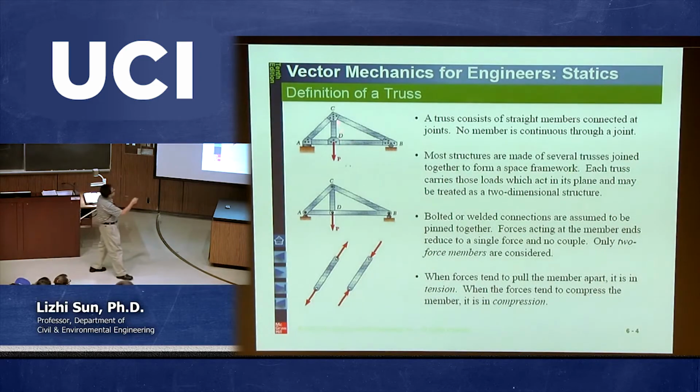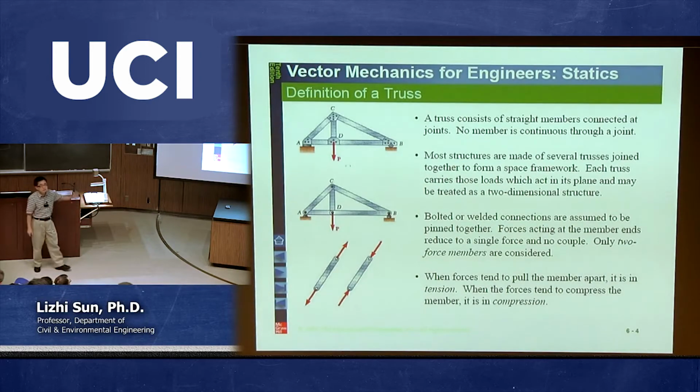So if you look at any one of these slender members, all the forces applied on it are at only 2 points. There's no third point somewhere in between, no additional forces acting in between. So for each slender member, there are only 2 forces acting at 2 locations. And if that's the case, this rigid body is called a two-force body.